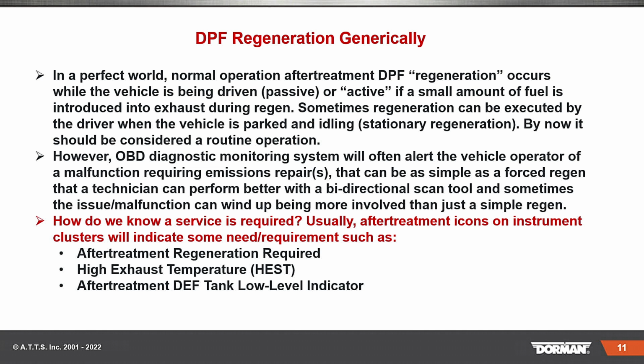DPF regeneration, generically again. Those of you that have to work on multiple different vehicles run into headaches: you're trying a regen, it isn't working, you have to go all over, why isn't it coming on, and so on. So generically, we'll take a quick look here. In a perfect world, and of course, you guys that work on these vehicles, we don't seem to ever have a perfect world, under normal operation the aftertreatment DPF regeneration occurs while the vehicle is being driven, passive or active. If while it's driving you don't have enough heat, a small amount of fuel is introduced into the exhaust during regen.